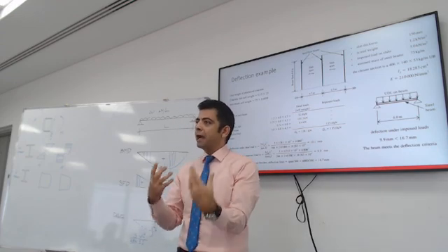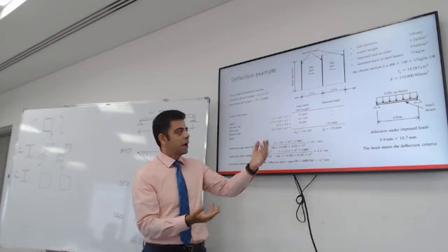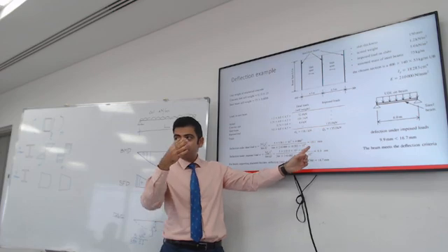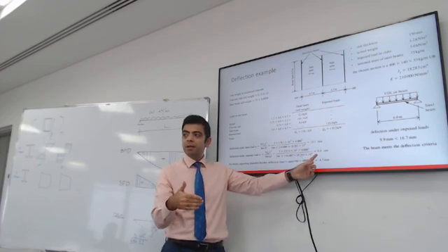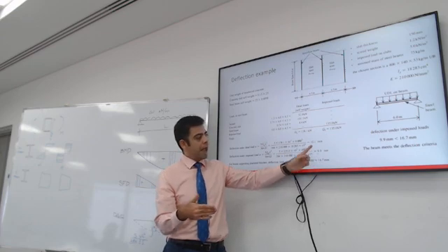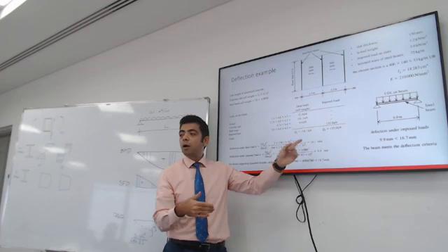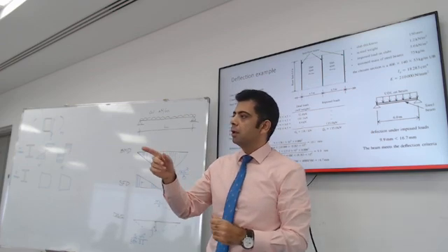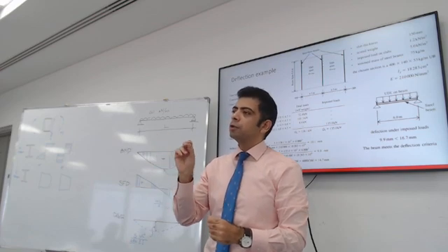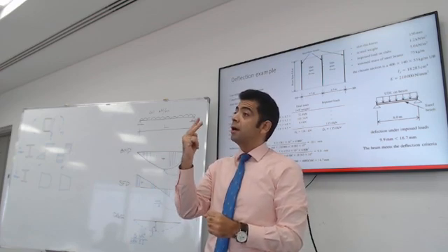How much is the actual deflection? Well, according to what load? According to the dead load, it will deflect 10 millimeters. Live load will deflect 9.9 millimeters. So should I add both and compare it to this? Or compare just one or the other? It depends on which code you're using. The Egyptian code will say check both.